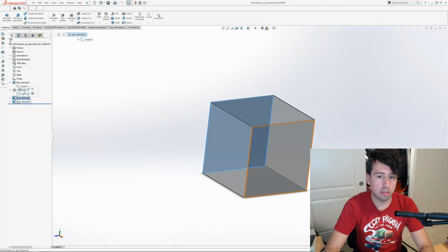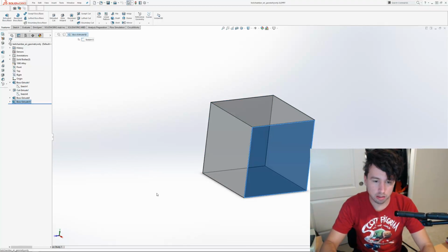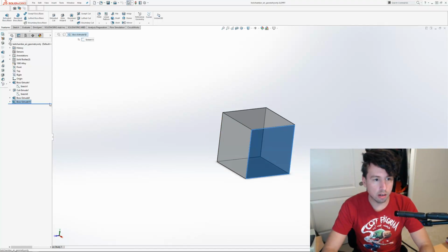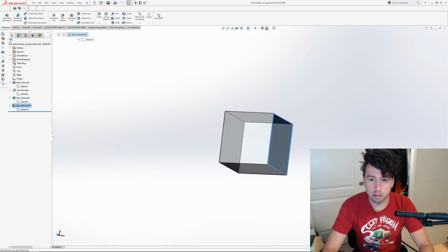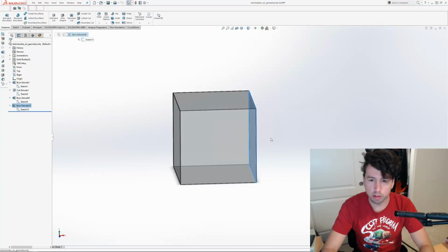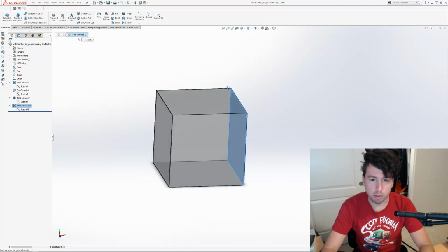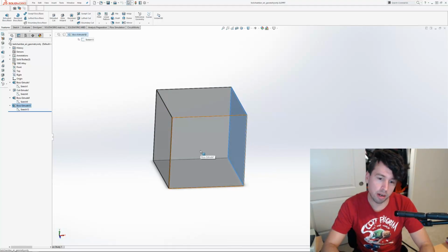And then SolidWorks Flow requires lids to specify boundary conditions. You can't just throw that body into Flow. You have to make sure that it's a closed volume. And so I just made lids. SolidWorks has a lids tool, so I don't think I need to go into that. This part is actually relatively simple. Just be careful about what your system conditions are if you're not using a box. If you're using any sort of complicated geometry, making a lid is something that might be a little bit more interesting, but for this case we have something simple.